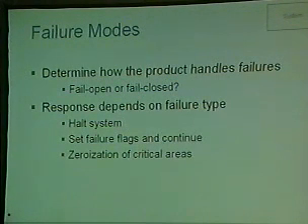It may require that the system's halted and to send some type of message to the crypto officer or whoever manages the device to come fix it. You may want to set a flag and continue if it's not a catastrophic failure. Or if you set up your detection circuitry properly, you can possibly determine an attack over time. If the temperature drops too fast, that may be an indication of a tamper event, and you may want to zeroize certain secrets out of memory.